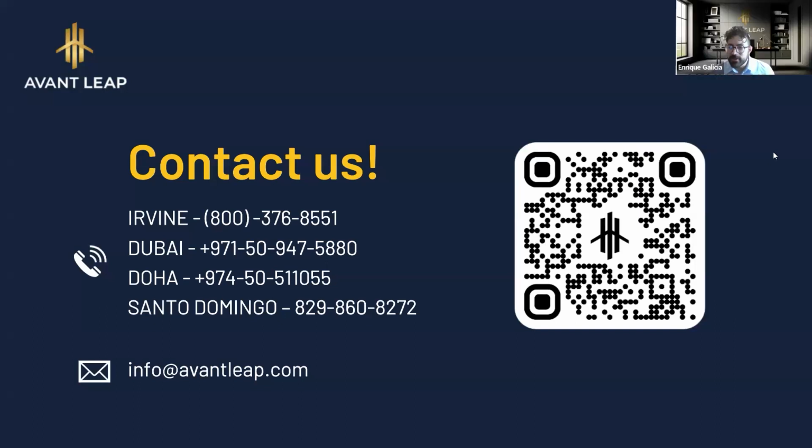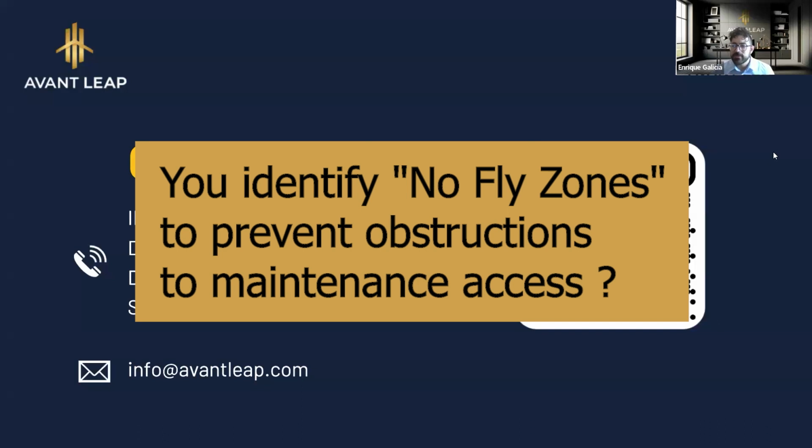A question from James Ward: you identify no-fly zones to prevent obstructions to maintenance? Yes, you can use something similar to the room structure. You can have a volume or a mass element that you want to avoid clashing with, so that all the elements that fall within this criteria shouldn't have any object inside of it. That way you can have obstruction types of clashes. It works similarly with rooms, because you want to find elements that go out of the ceiling, and if they are lower than that, they should clash within a room.